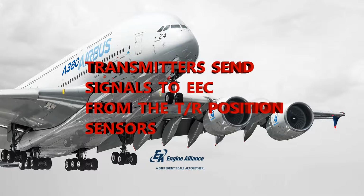There's transmitters that are going to send the position of the thrust reverser lever. It's going to be going to a couple of interfaces. Number 1 is going to be your EEC, your electronic engine control, and also your EIF, which is your engine interface function. Those are the 2 computers that it's going to be sending it to.